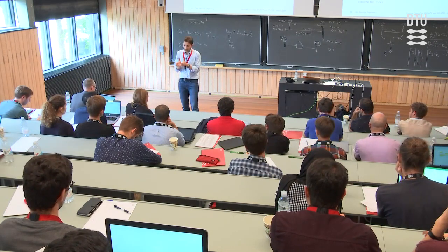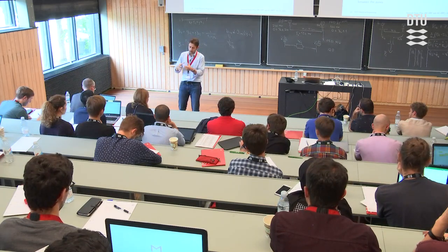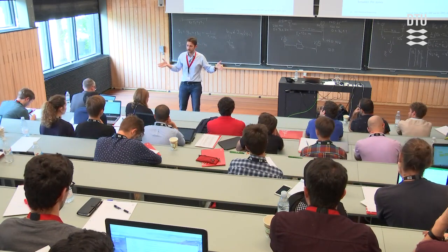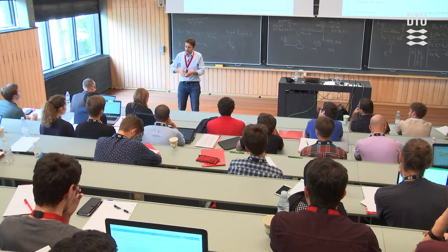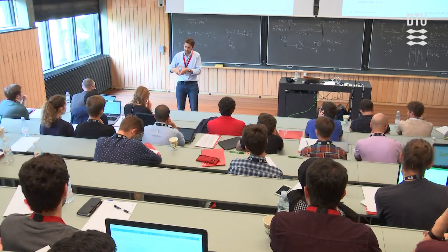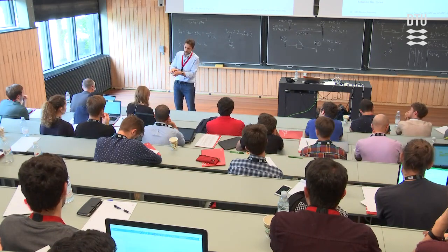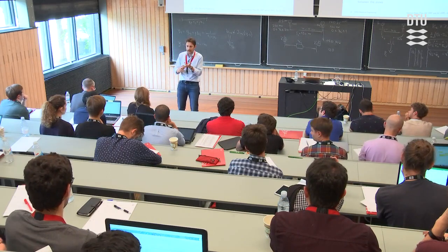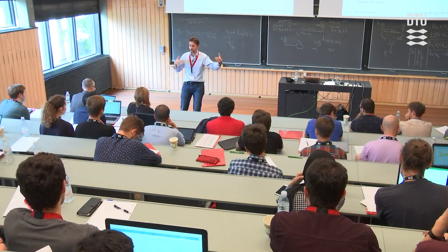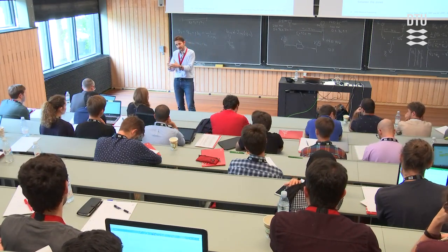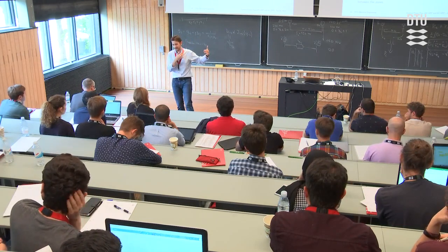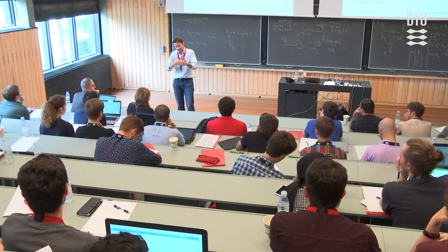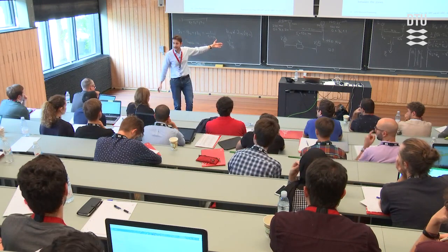Okay. So this has an aggregated limit. So for example, Germany and Denmark has maybe, I think, 4 or 5 different lines, AC and DC. They aggregate them all together, and they take the sum of their capacities. It's not going to be exactly the sum. You have to subtract a lot of that capacity because you have security constraints, you have maybe other issues, but it's going to be some capacity between these two countries. And then, because most of these connections are AC, this is not true for Denmark and Germany, but Germany and Netherlands if you want. So then you have to have some kind of reactance, right?